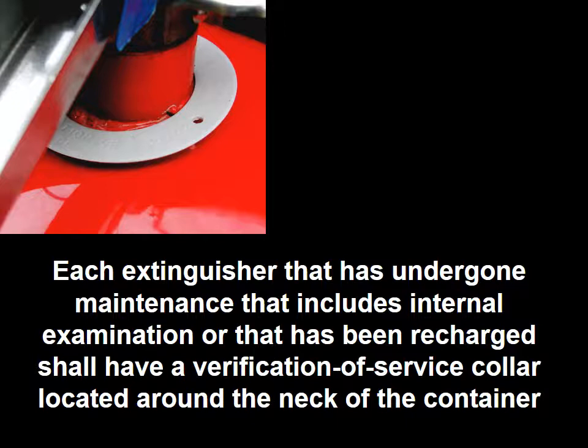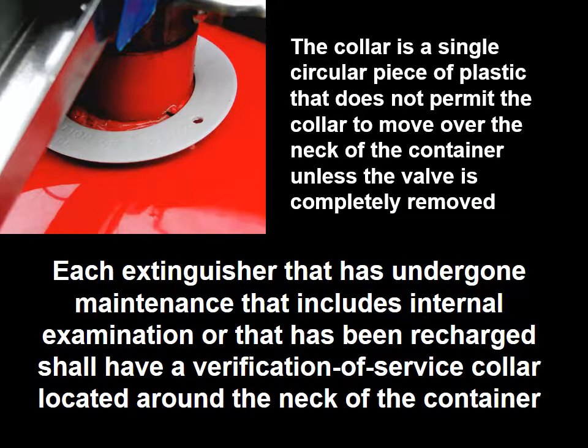Each fire extinguisher that has undergone maintenance that includes internal examination or that has been recharged shall have a verification of service collar located around the neck of the extinguisher. The collar is a single circular piece of uninterrupted material that does not permit the collar to move over the neck of the container unless the valve is completely removed.